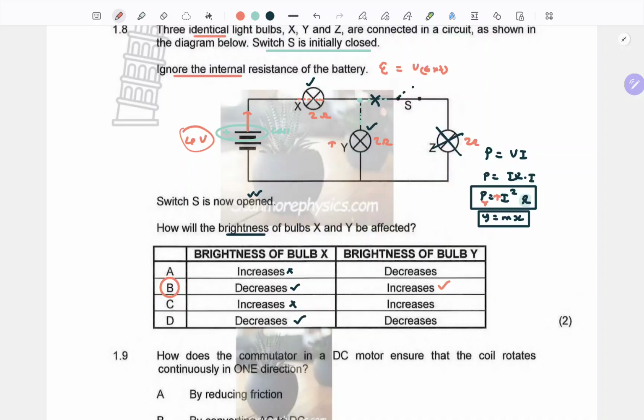Now we can clearly see that under the first scenario, I'll call it Roman figure 1, the total external resistance here is going to be basically 2 ohms plus the R parallel, which is going to be product over sum, isn't it? So 2 by 2 is 4, divided by 4, it's 1. So basically this is going to be 1 ohm.